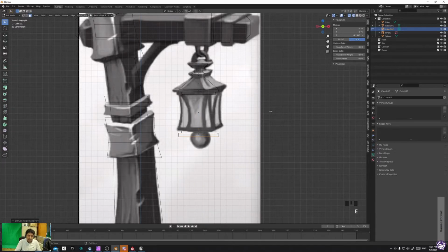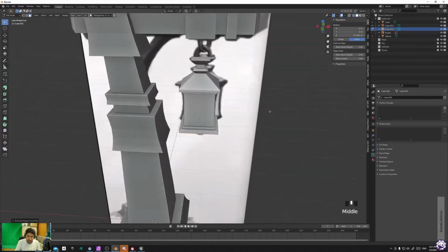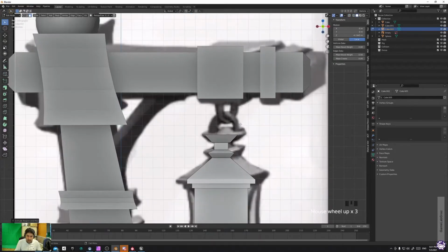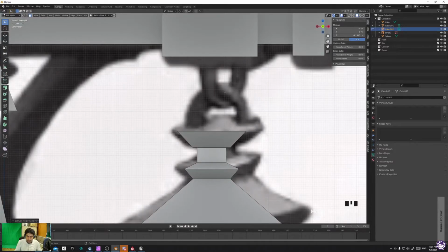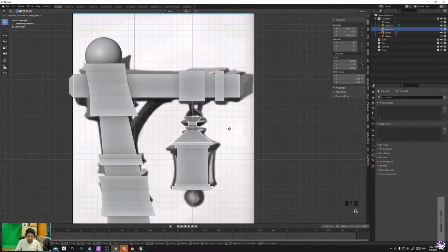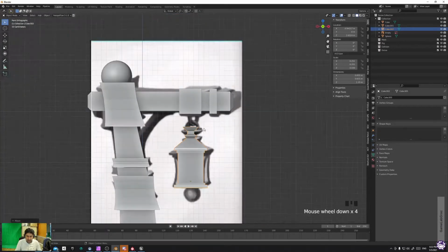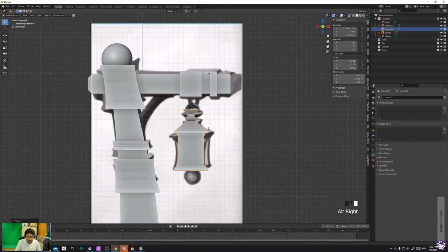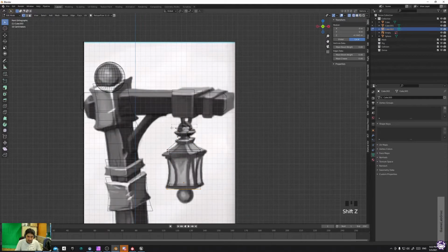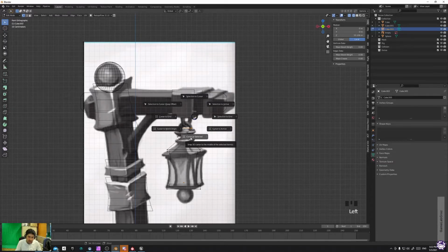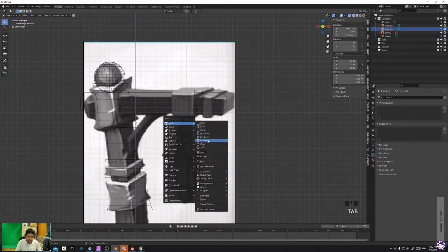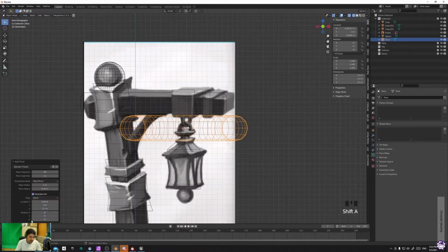That's it. Okay, that's good. On top of it, we have somehow a torus shape that is cut, but I think it's too low. I will bring it upward. In order to add the torus and make it exact, I would like to create it exactly at this point. First, I will select these vertices. By pressing Shift S, I can define the position of the 3D cursor, and I will select cursor to selected. And if I now create a torus, it will be created at this point.